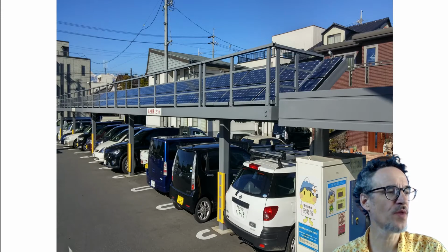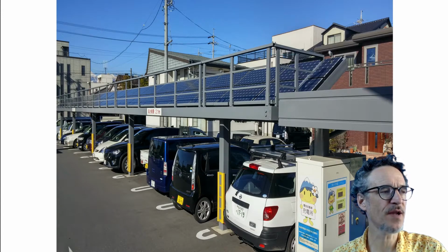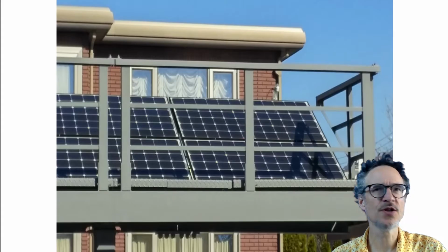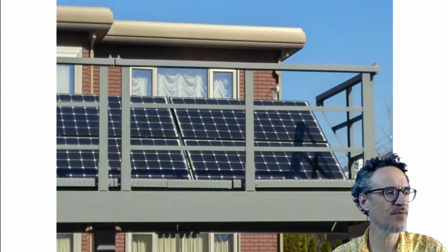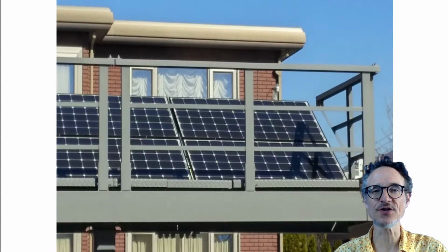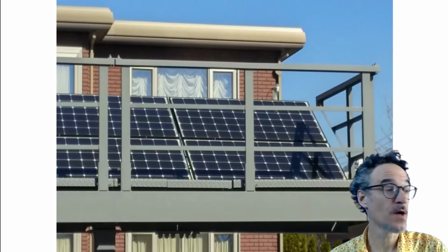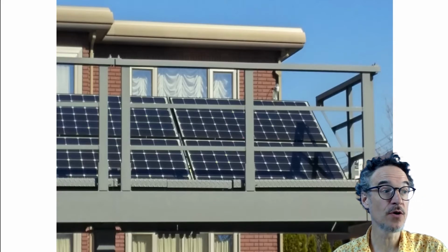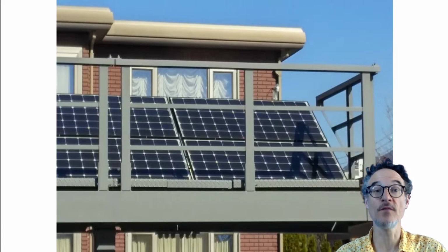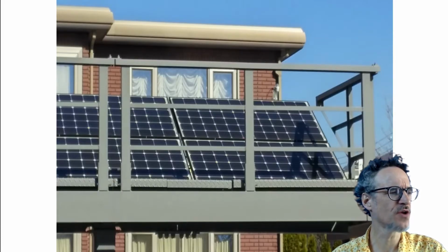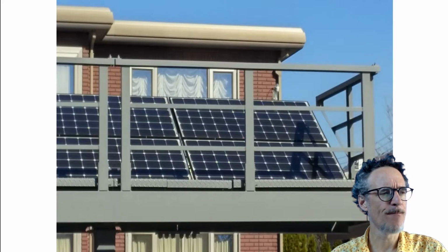So this is what's going on within the cells. I have a picture, by the way, and this worries me a little when I see this picture. Just a close-up, we can see that they've put railings around the solar panel for some reason, and the railings are shading the panels, and if we're not careful, this shade may cut off the whole of a panel or the whole of a module. So this is not a terribly good idea. I need to go and tell them about this.